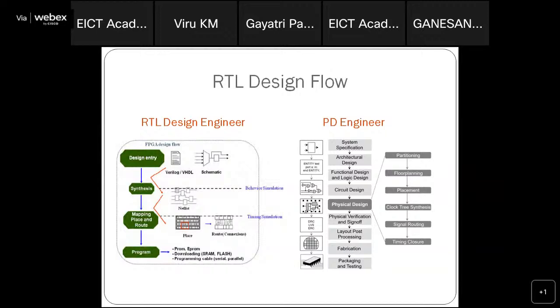If you are using Vivado, Xilinx ISE or Quartus, you will get some default customized IP from the tools, like SPI, UART, Ethernet, DDR3 and PCI. All of these come as IP, so from that also you can build your design and convert it into simulations. Once the design entry is completed, next you go to synthesizing.